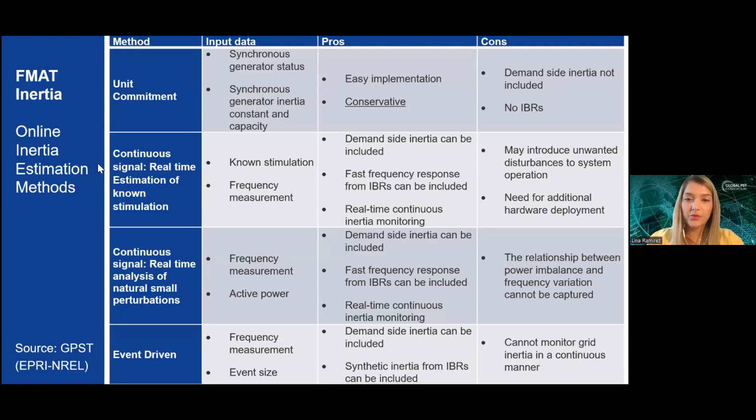Regarding natural small perturbations, the good thing is that we can also track demand side inertia and fast frequency response, considering the response that IBR can provide during the resting period. It's also real-time continuous inertia monitoring, but there are some trade-offs regarding the relationship between the power imbalance and the frequency variations, which cannot be captured as we don't know where the small perturbation is, and tracking that relationship between the imbalance and the frequency variation.